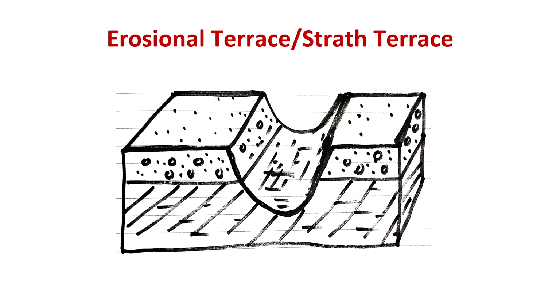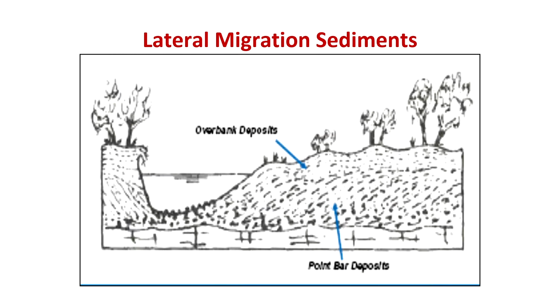So you have alluvium here, and lateral migration, as I have shown in one of the slides where we were looking at the cross section. So we see a lateral migration of the channel on this side, and this is typical of meander channels. So you will have the greater depth here, higher velocity. This bank will be the erosive bank, and this will be a depositional bank.